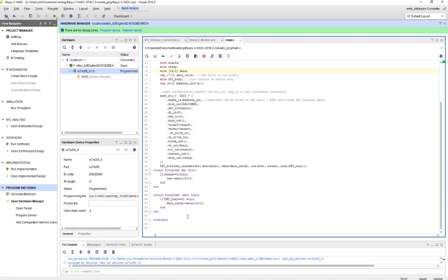Okay? So whenever BZ becomes 0, the upper byte of the data of the XADC is sent to data latch, which is a register type in the top, and that one is directly shorted to the data input of the SPI. That's how the code works. But eventually it didn't work. The code works, right? But it didn't change the error messages we received, the 8 error messages.